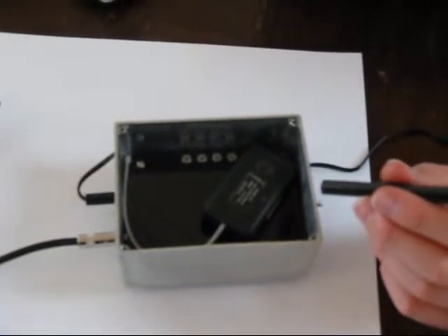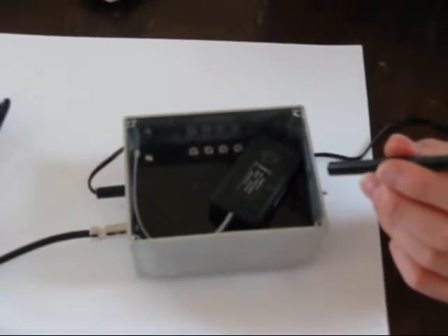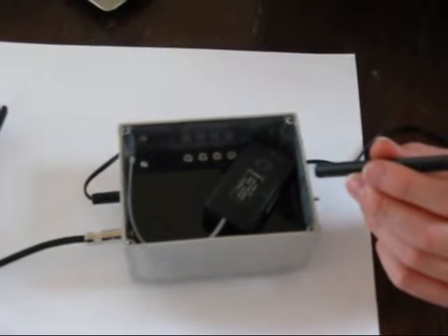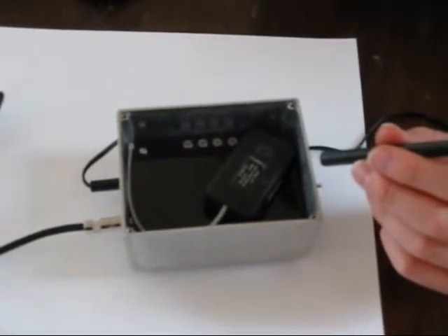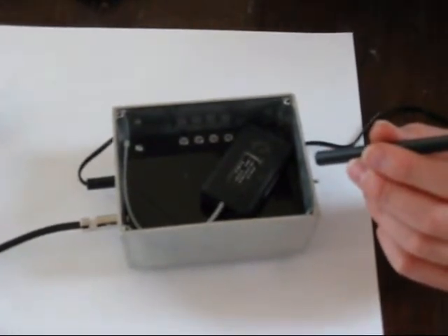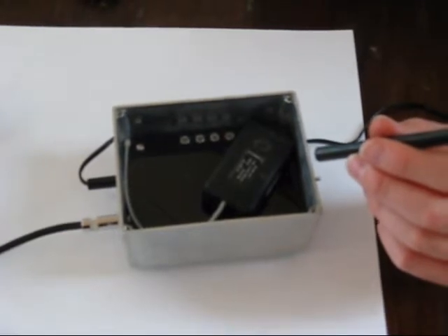After you have taken the magnet pen away, you need to listen for up to 5 seconds to check that no pulses are received from the transmitter. This ensures the transmitter is fully off. Please turn off the transmitters.